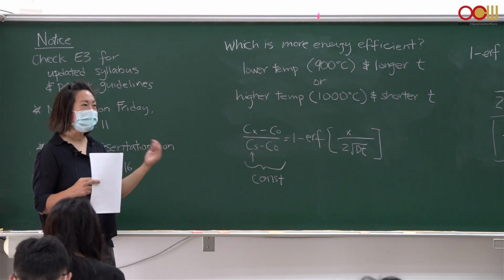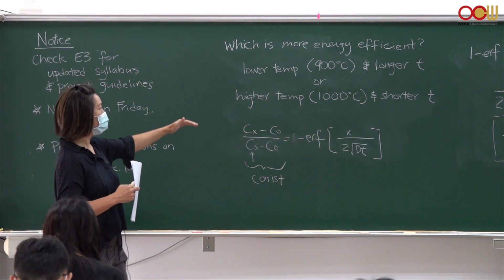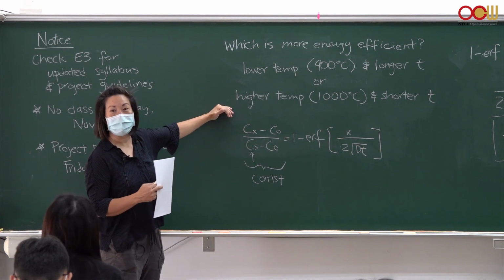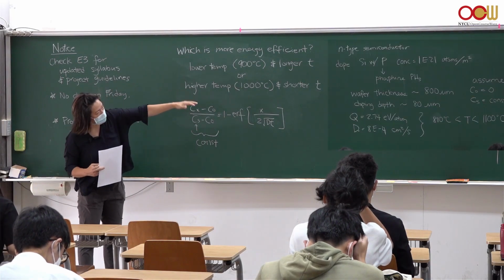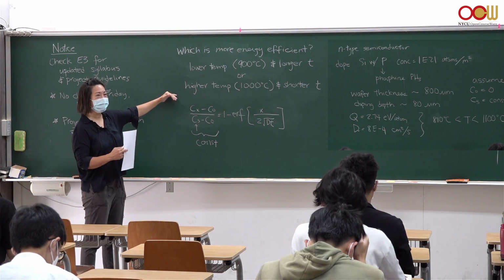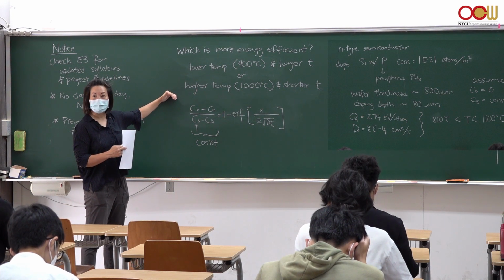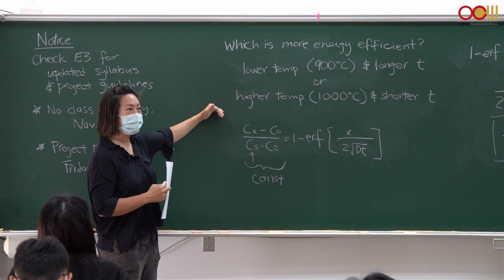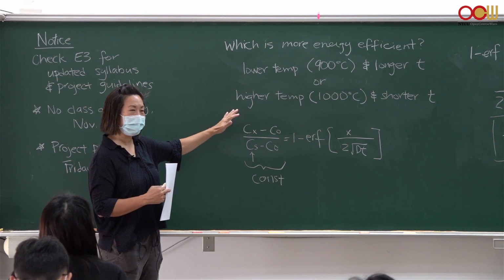And so my guess as well is that it would be better to heat at the highest temperature you can, which is a little under 1100, at the shortest amount of time possible, because the difference in time based on a small temperature change is so big.